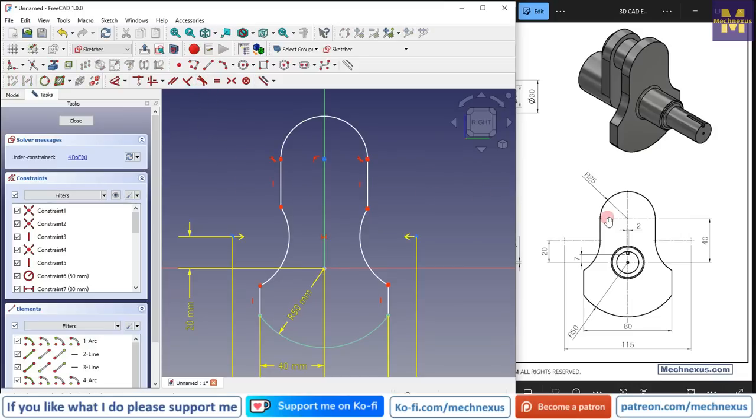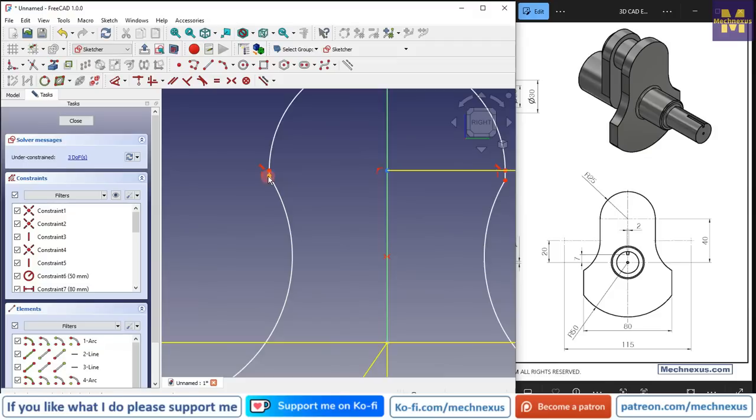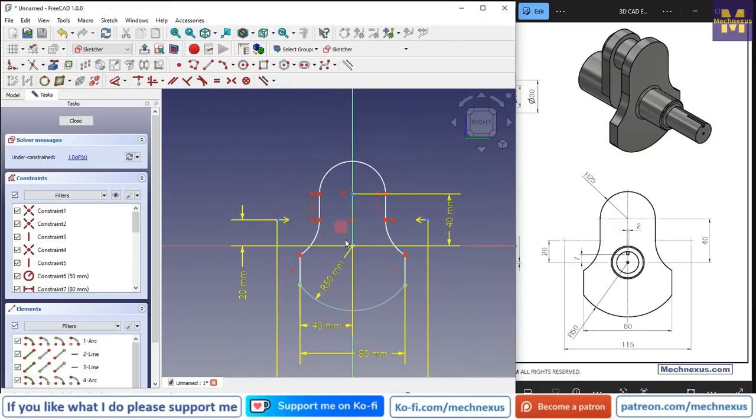Now from this center to this center is 40 mm, so we will select a smart dimension and provide 40 mm. And now here we will stretch this line on both sides, and we will add a tangency on both sides, left as well as on the right side, so add a tangent.